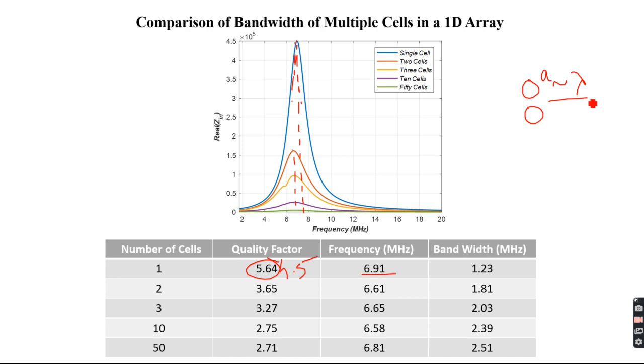If the aperture size is, let's say, lambda by 16, then this frequency is going to shift more. But if it is like lambda by 2 or lambda, then it's not going to shift much, I guess, because with smaller aperture size CMUTs, the effect of mutual crosstalk is going to be more prominent. There will be more spurious resonances that you're going to see.